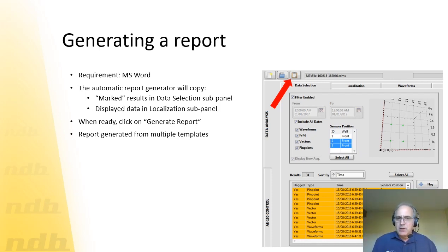So you close it, everything's okay. One thing, if you're working with a laptop, before closing the lid of your laptop, close Miradar. Sometimes if you run out of battery, Miradar doesn't have time to close the session, and then you get in trouble. So close Miradar before shutting down your computer or making it hibernate.